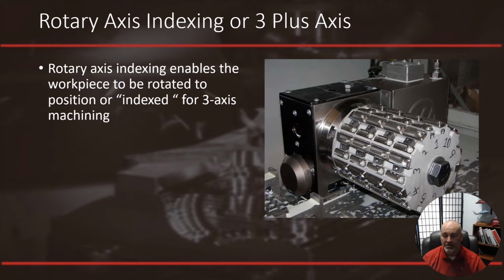This increases the amount of cycle time so the operator can do other things. So for example, every time this stops, I would imagine they're taking operation 1 parts out of a vise, taking op 2 off, that's finished parts, putting the op 1 components in those places, and then loading new blanks. While that's running, the operator could be deburring or doing secondary operations on those parts.